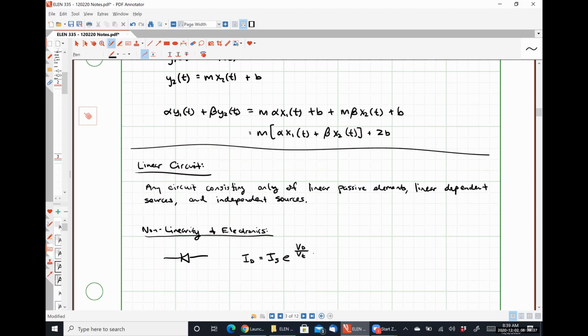And we are also going to be doing small signal analysis, which effectively means we're going to look at these circuit elements at very specific operating points and subtle variations above and below that operating point to see how they behave. Because if we look at one part of its operational curve, we can get a linear approximation of what's going on.